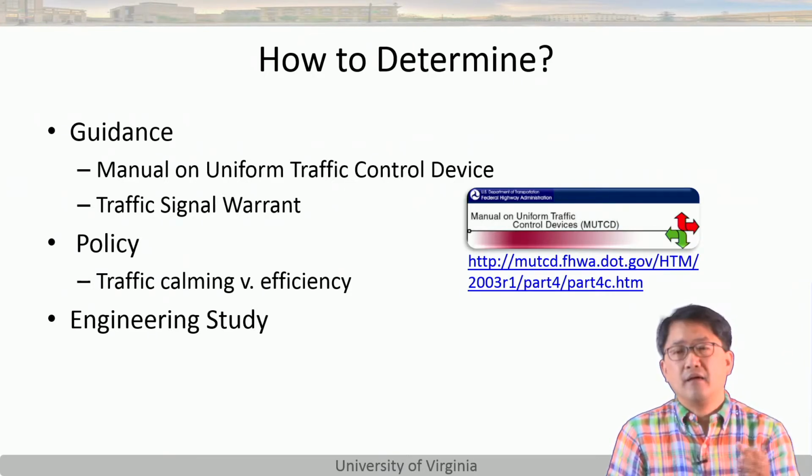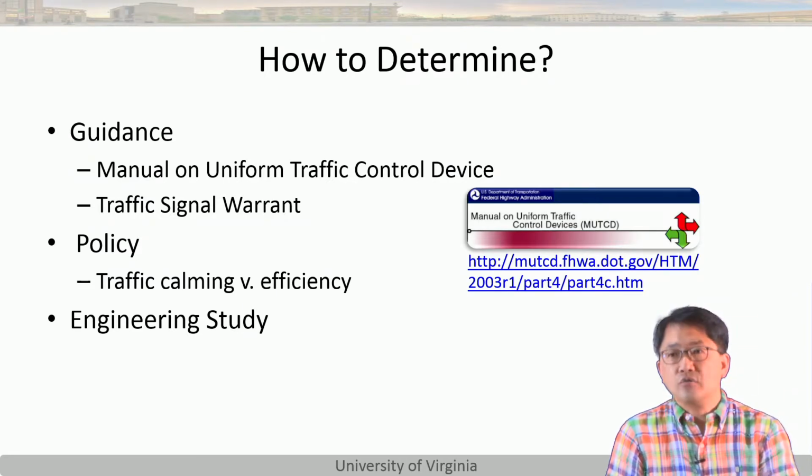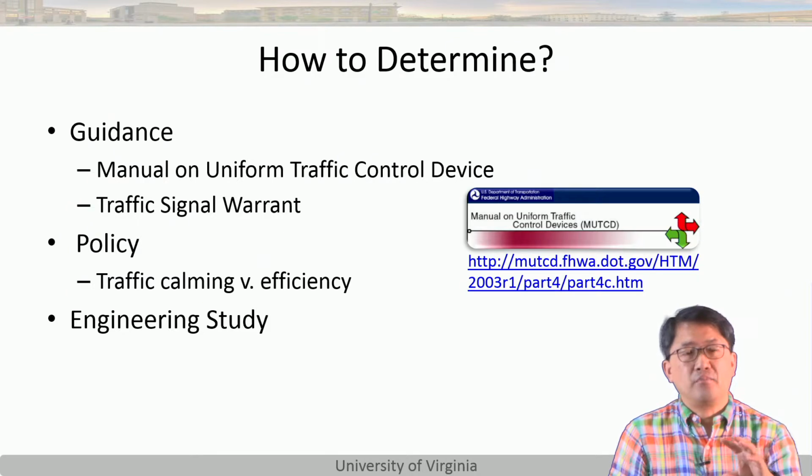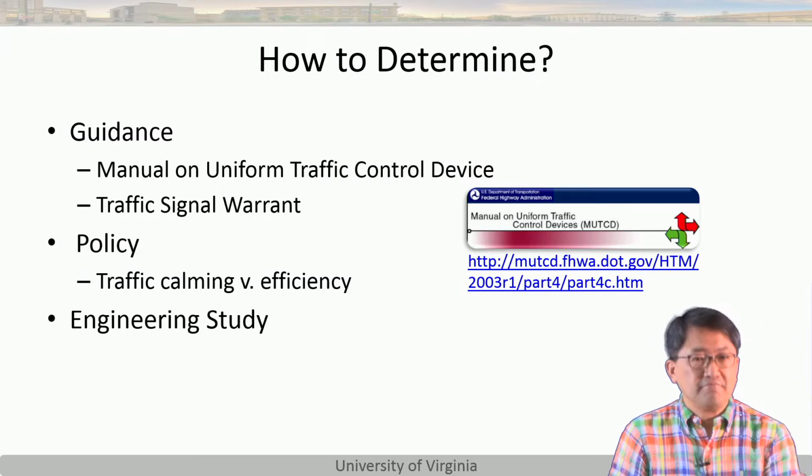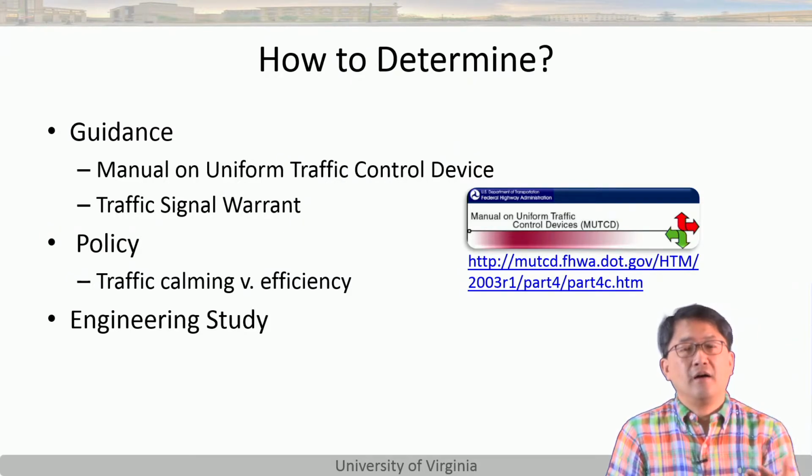It's basically triggering what we call an engineering study to figure out whether we really want to install a traffic light. And this usually goes with priorities. So you have maybe X number of intersections that actually met the warrants, and you don't have money for 10, usually you don't. And you have to set priorities.